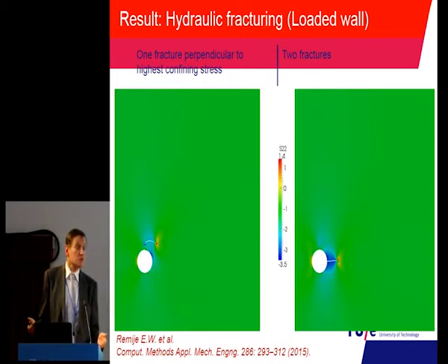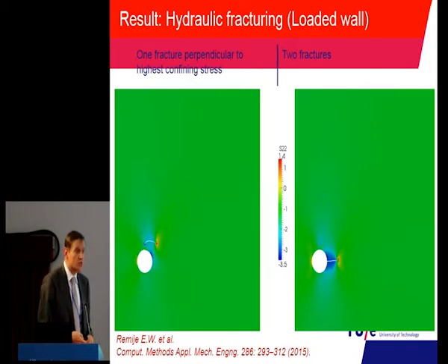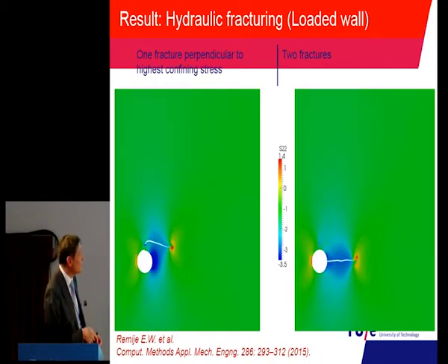Now, the advantage of XFEM, typically, what is it? It is that you can take a rough mesh. Now, if you start using a fine mesh around the crack, you're basically losing your advantage of XFEM. So we launched the idea to include steps of pressure between the crack and the surrounding. Instead of taking a continuous variation of pressure, we took for the pressure exactly the same expression as for the displacement. So a jump in pressure from one side of the crack to the next.